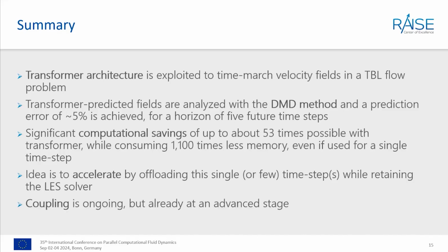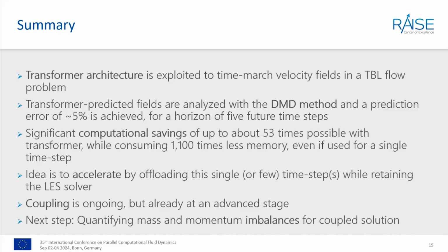Coupling is ongoing, but already at an advanced stage. The important thing to consider once this coupling is achieved is to quantify the mass and momentum imbalances, because that's where the convergence might be difficult for the CFD solver.